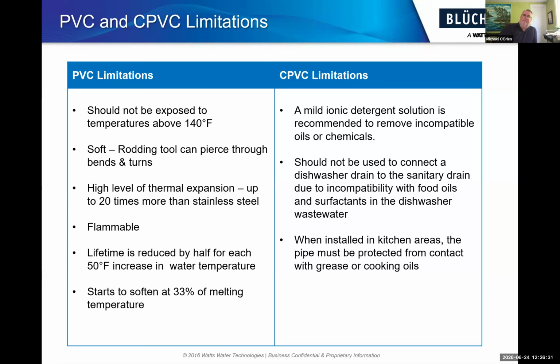So some people would say, well, CPVC is the way to go because it can handle those high temperatures, and yes, it can. The problem is that it's not really compatible with regular detergents or surfactants and food proteins. The actual material to make the CPVC products, on the MSDS sheet, it says should not be used to connect a dishwasher drain to the sanitary drain due to incompatibility with food oils and surfactants in the dishwasher or wastewater.